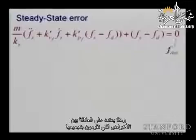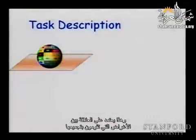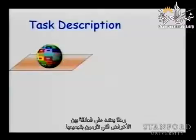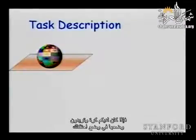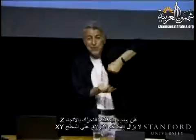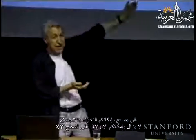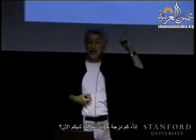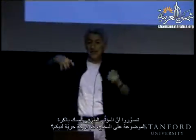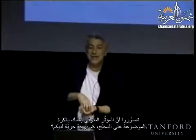And these depend on, I'm going to skip this, these depend on the relationship between the object you are assembling. So if you have a sphere, and if you want to put the sphere on a contact, you lost a degree of freedom, right? You cannot move in the z direction. You can still slide on the xy plane, right? So how many degrees of freedom of motion do you have now? Imagine the end effector is holding the sphere on the surface. How many degrees of freedom do you have?